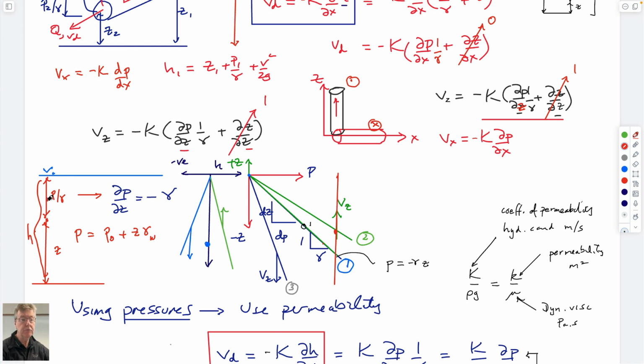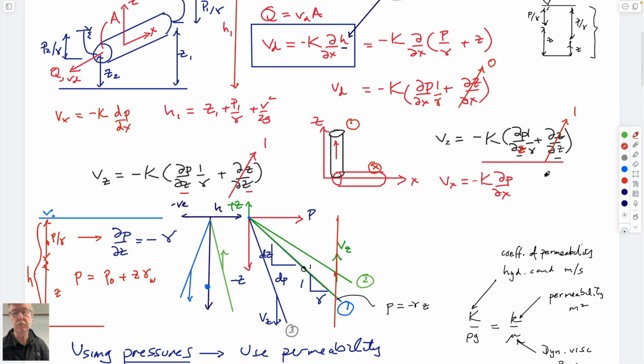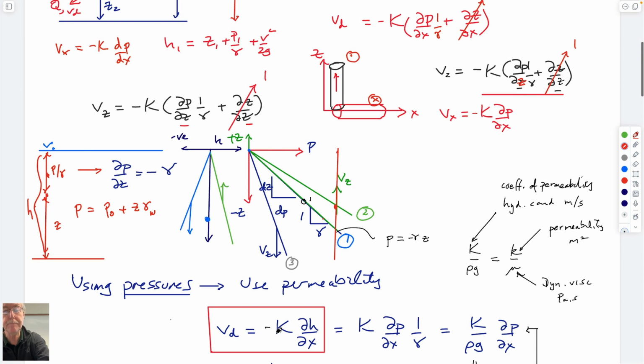This point here, the pressure would be equal to the depth of this below the surface, and the elevation would be the depth above the datum. Every single point along this, if the fluid is static, has a uniform head, and therefore is not flowing. And so it's kind of a complicated thing to think about if you do it in pressures, that you have this extra term here if you're moving in the vertical direction. But perhaps it's relatively straightforward to understand it in terms of what it means in terms of heads. So you just need to remember that.